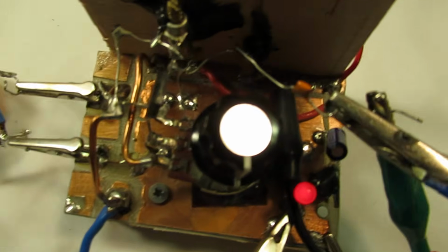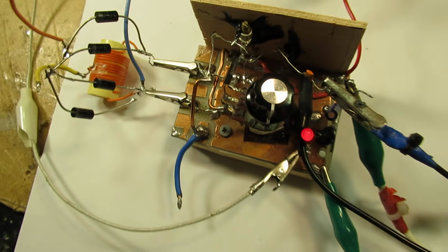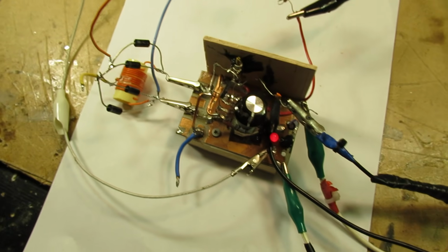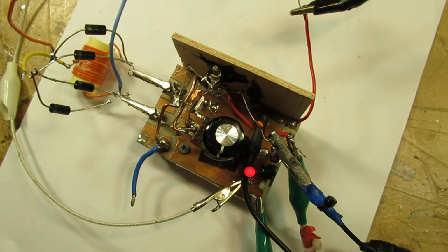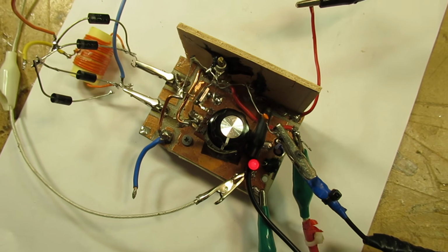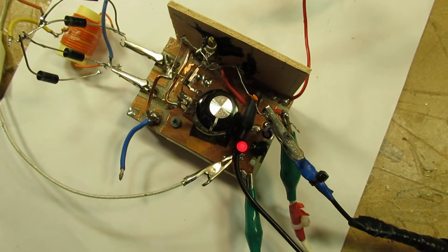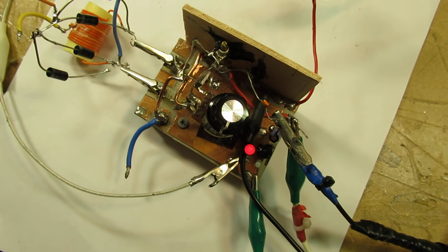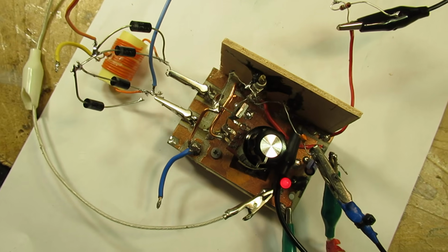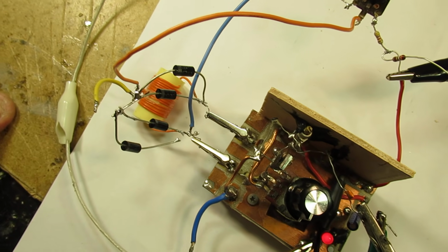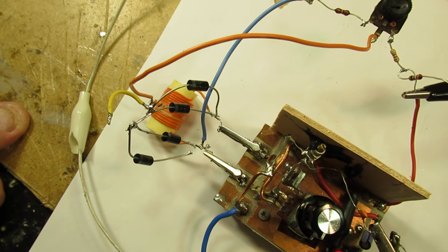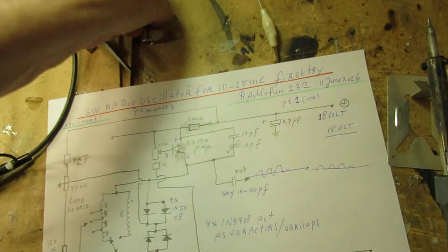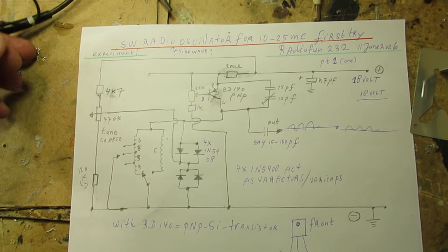We set the bias of the oscillator here with that potentiometer, and that's very, very important. Of course, you have to find a setting of that potentiometer that biases the oscillator to a position where the coil that you want to use, for a certain frequency, works. Anyway, so this is the schematic now, and of course it's completely experimental.